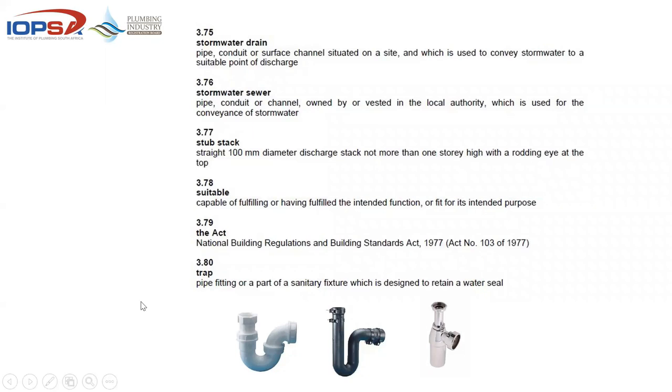Suitable is a generic term, that you could have anything, but it means capable of fulfilling or having fulfilled the intended function, or fit for that specific purpose. There's a lot of drainage material that does not necessarily have a standard or a spec, but it could be considered suitable for that purpose. The Act, the one that we've been dealing with up to now, is the NBR, the National Building Regulations and Standards Act.